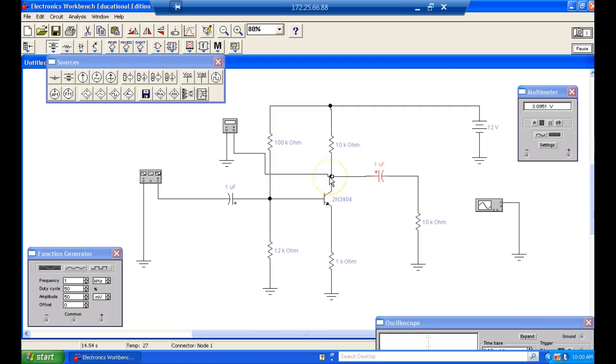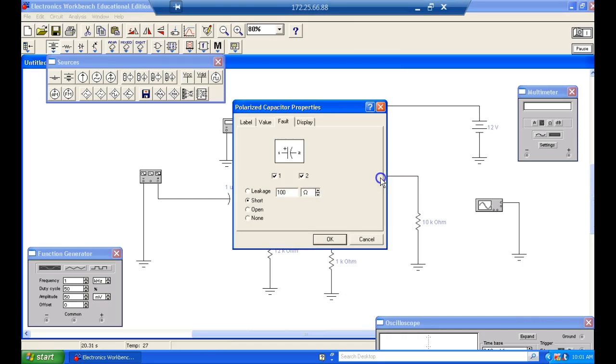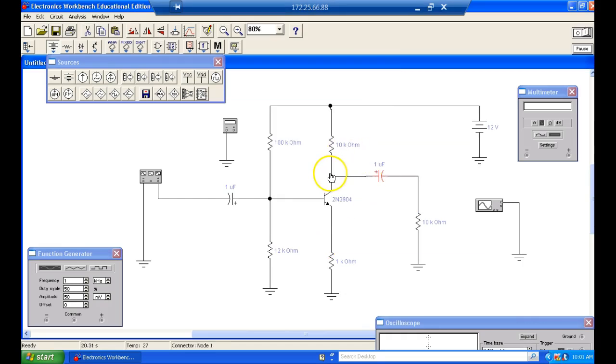And why? Well, when we calculated that bias voltage, this guy right here was an open. This guy here was an open to DC. So that means that this current that was setting that voltage right there, this resistor, we just ignored it, because bias is a DC voltage, right? You understand? Yes or no?